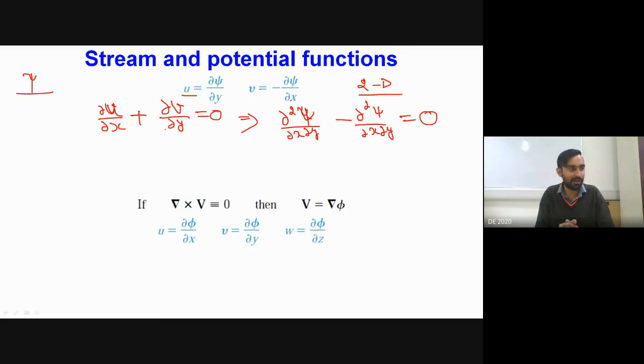Okay, and at the same point of time, one additional advantage we are getting is that both the different components of velocity, u and v, are now accounted into a single variable psi. Okay, so now if I substitute this formulation into my x and y momentum equations, there also I'll be finding that my equation will be of two-dimensional nature, and I'll have only psi and p as the unknown quantities. Okay, another type of